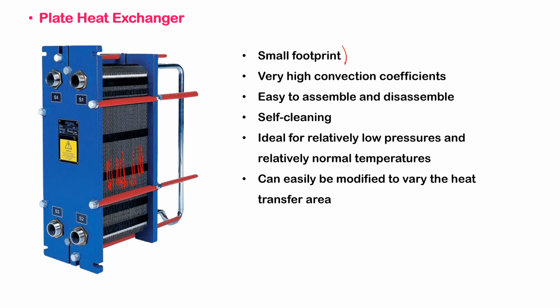One advantage of this kind of heat exchanger is that it is easy to assemble and disassemble. You can unscrew it from the side, and if one of the plates is rusty or corroded, you can just remove it and replace it. Or you can even clean it if dirt builds up gradually. One issue with this kind of heat exchanger is that you cannot use it at high pressures because it is a semi-open design.